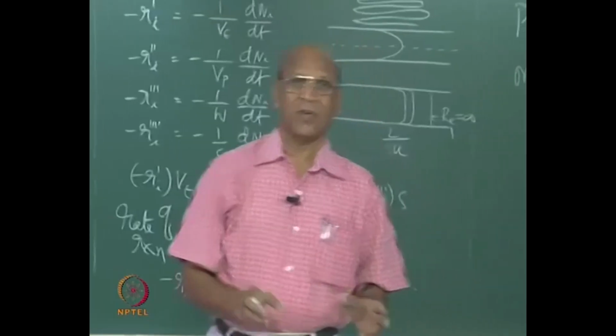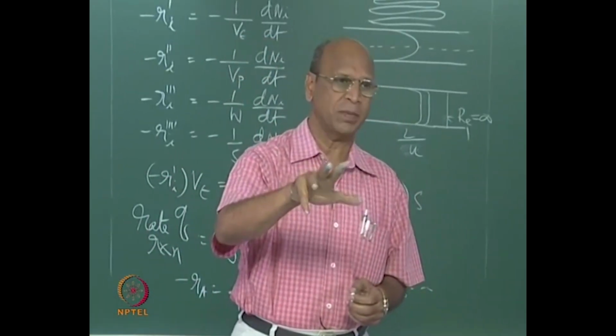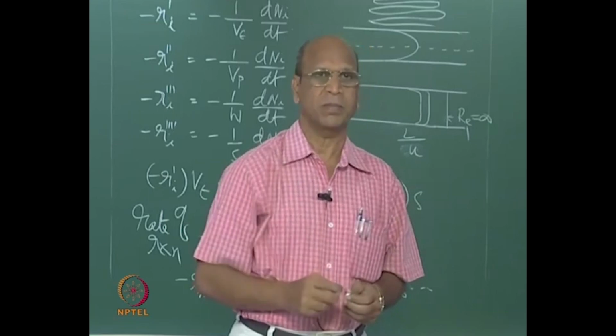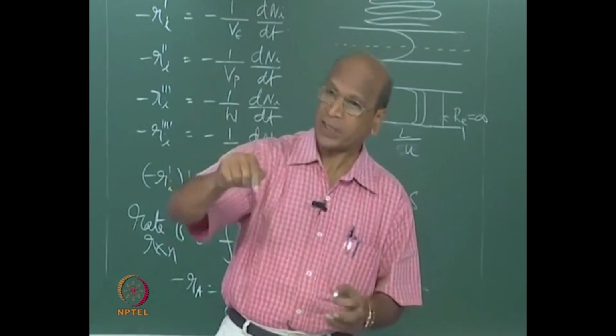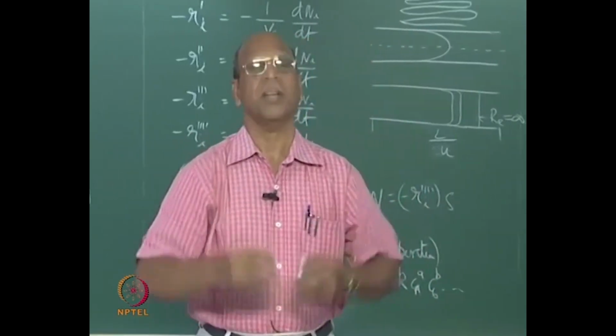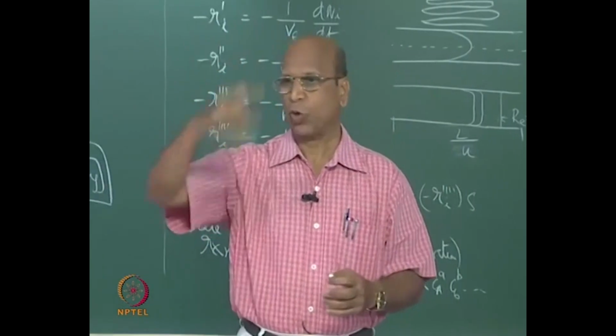Gas reaction in CSTR. You can do. Residence time is less, so you can do it. Okay. Theoretically you can do it, but no one will do it. Why? The reason is that the concentration of gas inside will be very, very less, diluted. Unless you go for very high pressures in the CSTR. High pressures, you can go to very high, 100 atmospheres, 200 atmospheres.